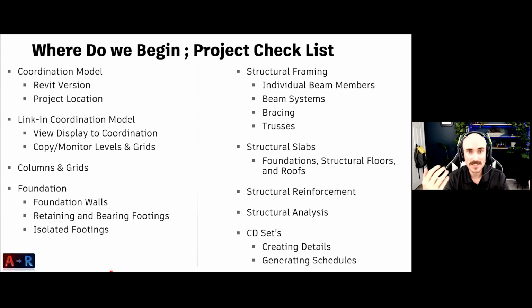Then you have your CD sets. So just like in AutoCAD, in Revit, you can create your CD sets, creating your details, and also generating your schedules as well. Again, those schedules are parametric. So if any of the data changes at any point in time, it will update with it automatically as well.